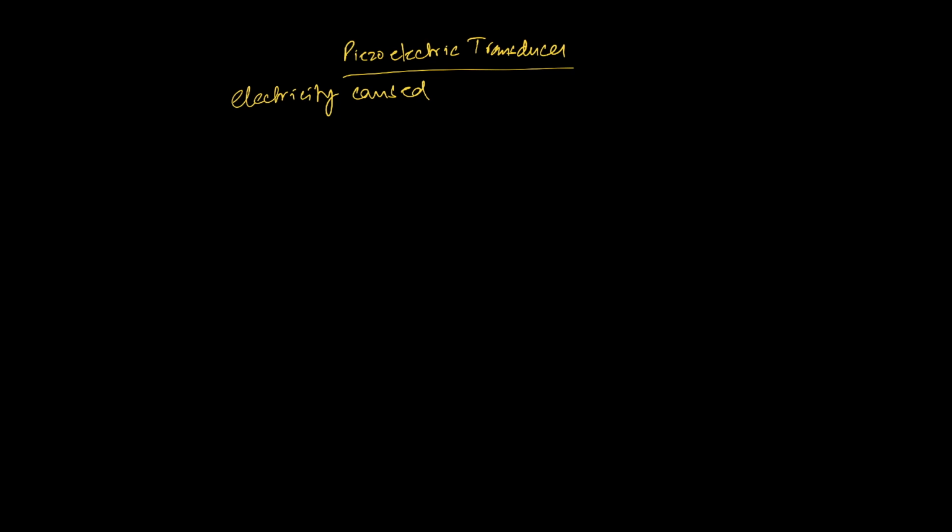The way I want you to visualize this is to think of a material like quartz. Not every material is piezoelectric, but some materials are, such as quartz. You can have quartz coated with a conducting material like silver. When stress is applied, like when you try and squeeze this quartz material, the ions in the material are going to move towards one of the conducting surfaces while moving away from another. So by squeezing or by causing some pressure onto something, you are generating electricity. You're generating a potential difference inside a system.